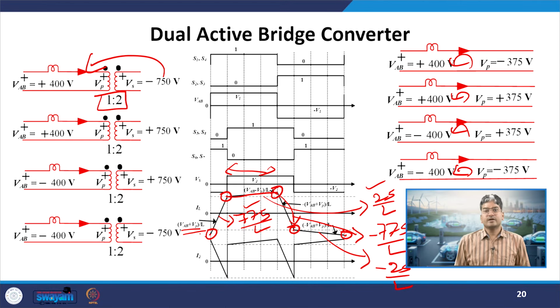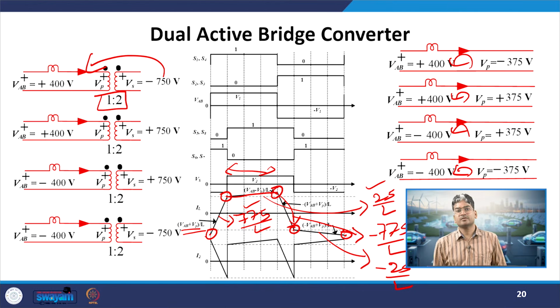So, what changes have we observed in this waveform? When the DAB is going for actual loading conditions, where the voltages will be different from the desired values, the inductor will be continuously charging and discharging. There will be no zero voltage application across the inductor. In mode 1, it will be charging at a slower rate compared to the previous case, where the nominal voltages were there.